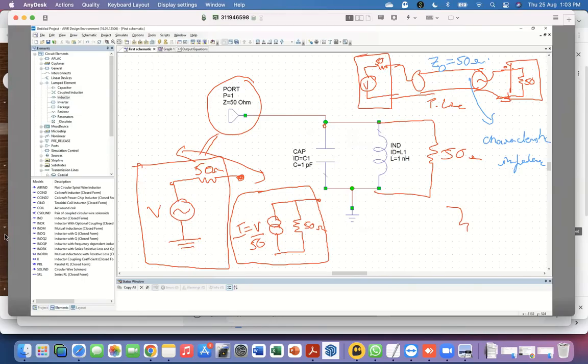But just to answer your question, if I looked at this just from a low frequency point of view, even though it is correct for the low frequency picture, it is not relevant. If I measure the resistance between this point, which is the center connection, and this point, that resistance will be 0 in the ideal case. Similarly, if I measure resistance between this point and this point, that resistance will be 0. So in the low frequency picture, this is just like you connected two wires between these two circuit points rather than connecting them directly to each other, right?